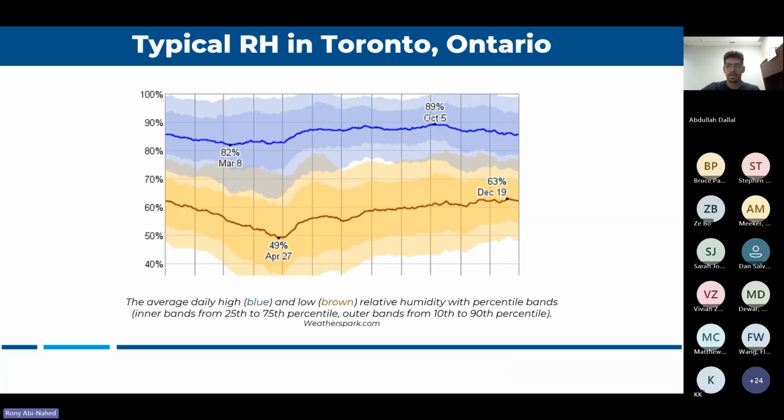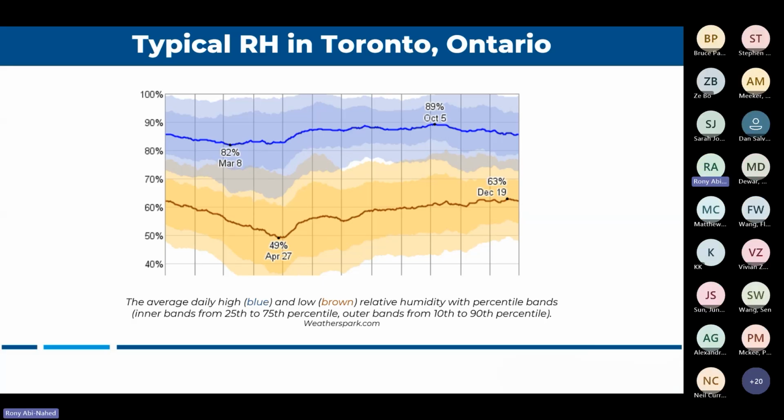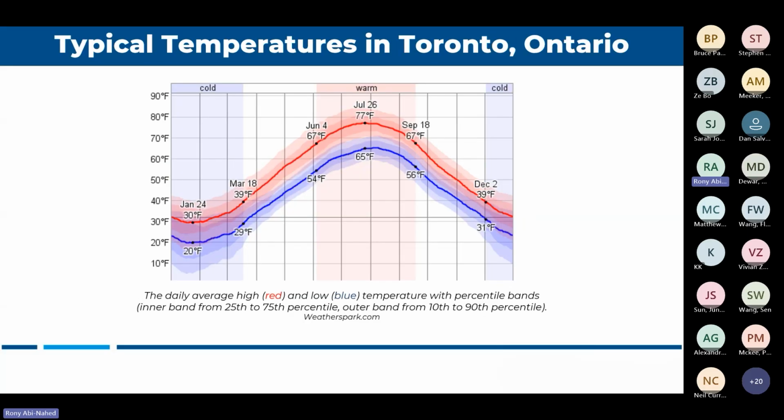So why do we need to humidify? Most of you already know why, but I'll go over it very quickly. If you look at the humidity itself, it's mostly constant the whole year. So it's not really the humidity that's the big issue for humidification, it's the temperature. That's where we have a big fluctuation between summer and winter, and that's mainly why we talk about relative humidity. It's relative to the temperature.